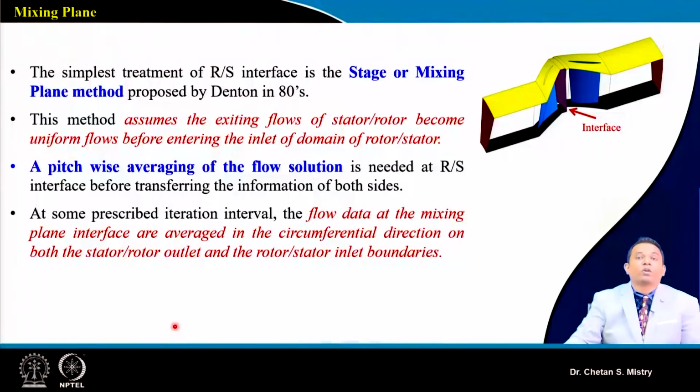So let's try to look at what we mean by the mixing plane approach. This is the simplest way of analyzing the interface between rotor and stator. What it does is it assumes the exiting flow from the stator or rotor, suppose I have an inlet guide vane before my rotor, or maybe I will be having a rotor.